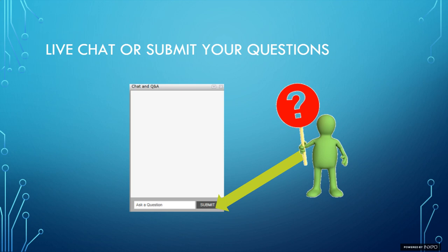And there are numerous ways to get that feeling about sleeping well. At least one of them we mentioned about the alarms and then closing of a valve. If you really have a super interest in the air quality, there are online sensors that are continuously monitoring, and depending on your degree of sleep or not sleep, you have to spend quite a bit of money for any leftover hydrocarbons or oil in the compressed air. It is very easy to do a pressure dew point nowadays. There are sensors out there that are very inexpensive, and you can put them in multiple areas.